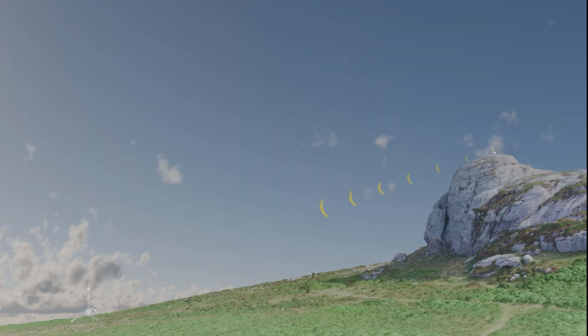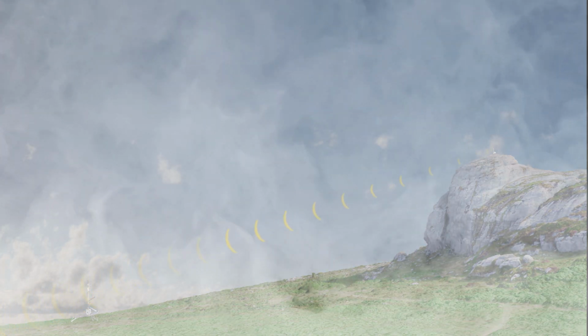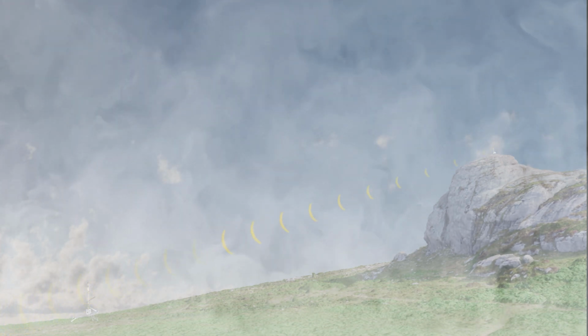Distance. As the signal travels away from the transmitter, it spreads out and weakens, reducing the signal level at the receiver. Atmospheric absorption. Water vapor, rain, fog, smoke, and snow can increase signal loss.